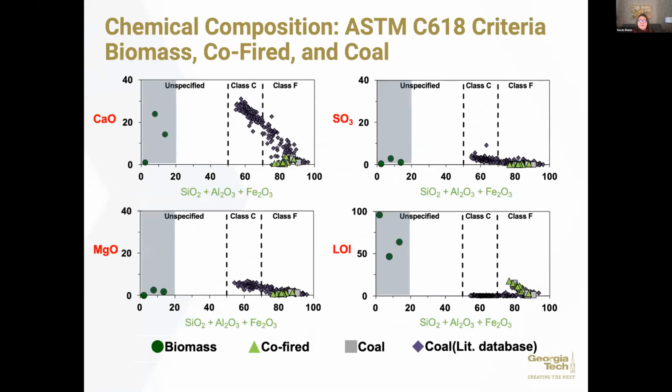So let's think about what this means for us, because now we have very strict standards in the United States for what type of ash can go into concrete. ASTM C618 governs what goes into concrete, and I believe these are changing. These rules are starting to loosen up a little bit, but in the United States, ash in concrete has to be completely from coal firing. Okay, so we can't have other materials present in there.